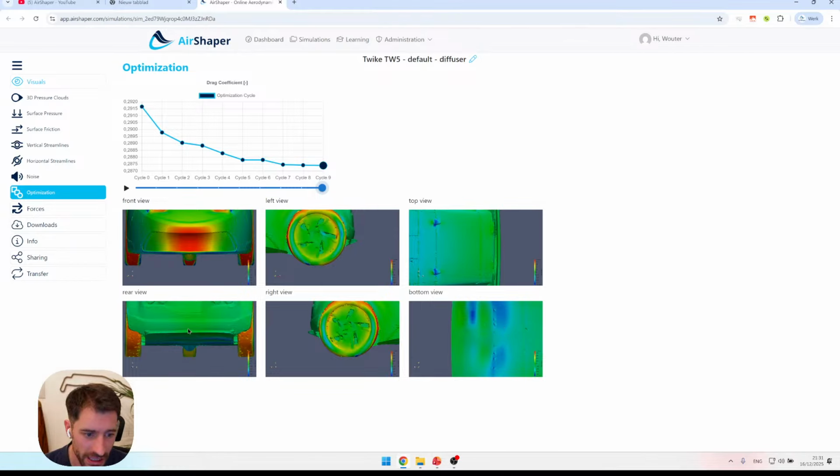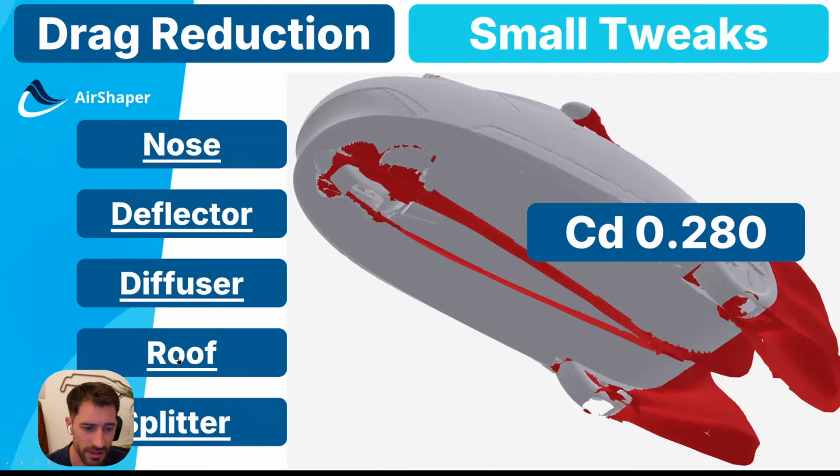So in the middle, it pushed the diffuser upward, which gave us an S curve actually for the diffuser, which means you're still pulling the airflow upward, but after you pull it upward initially, you flatten out to make it go horizontal again to recover some of the pressure loss so that you don't have this suction effect, which would actually generate drag on your car. And this has been key for future iterations on this car.